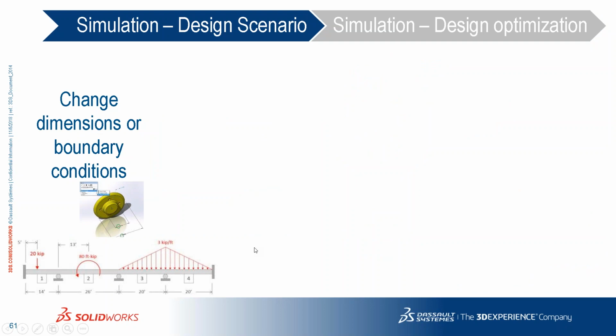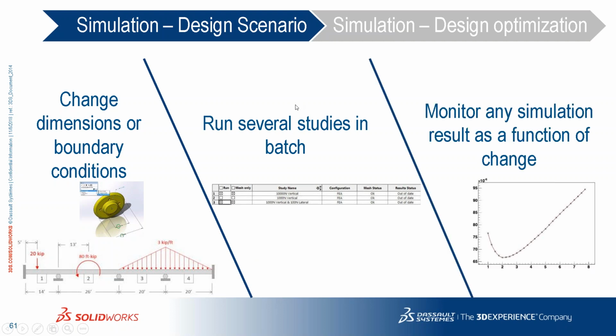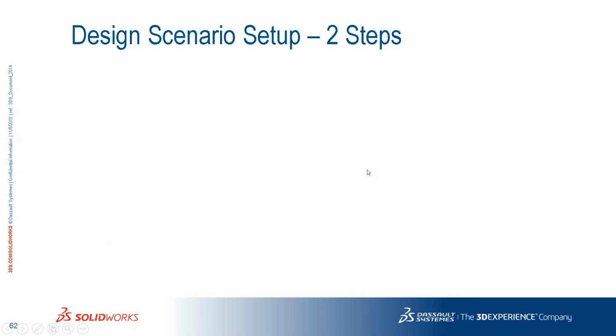So what is a design scenario? It's again a table, a tabular interface where you can change dimensions or boundary conditions, which can be a force, a mesh parameter, or a prescribed restraint. The table allows you to launch several studies in batch, and then you can monitor the variation of results as a function of the parameter change.